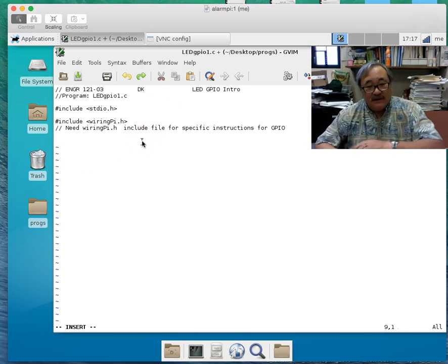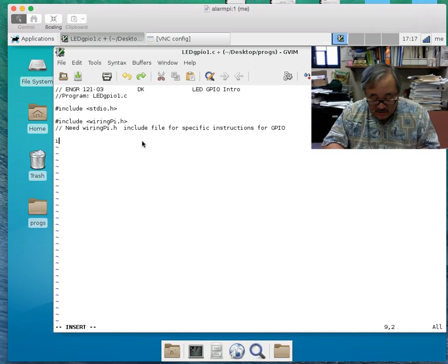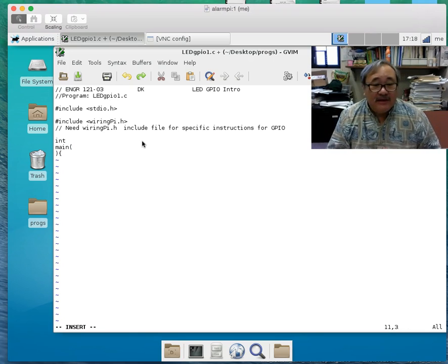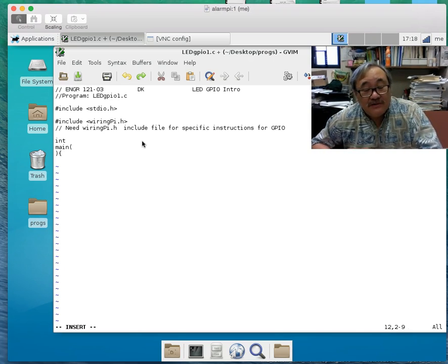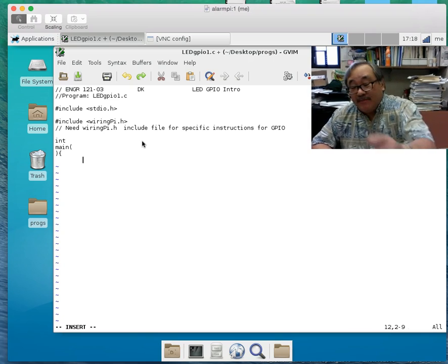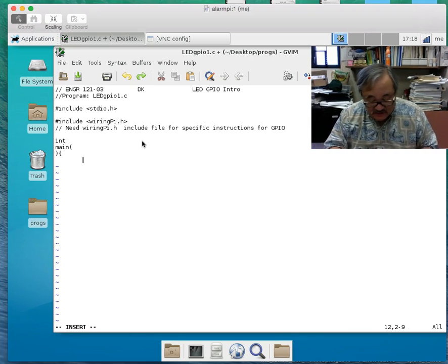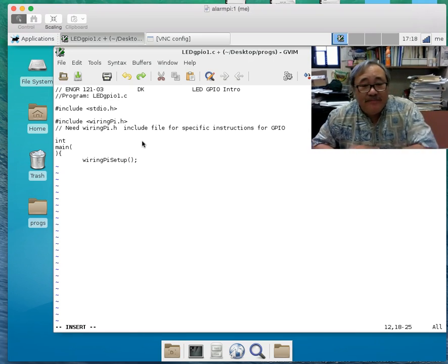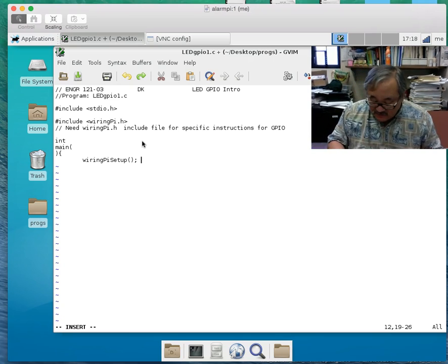All right, so now I'm going to go ahead and start my program. And then Dr. Mayhew likes it like this. Okay, like that. And I am going to start writing my program. The first thing I'm going to do is go ahead and set up my wiringPi. In other words, initiate the wiringPi to set up my 40-pin connector. So I'm going to say wiringPiSetup. There we go.